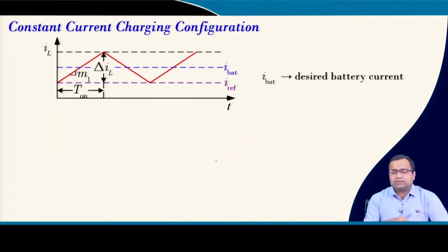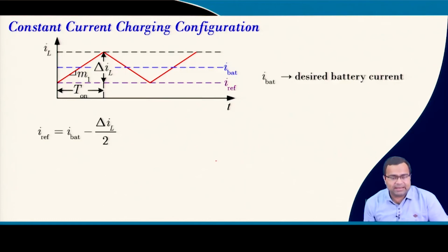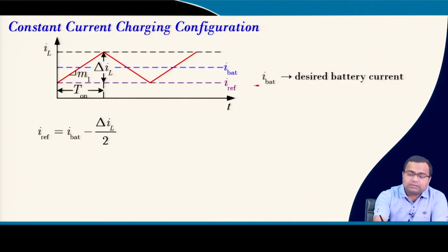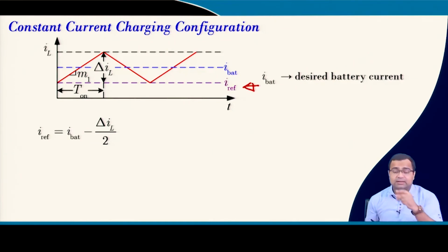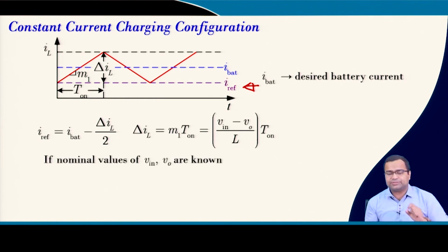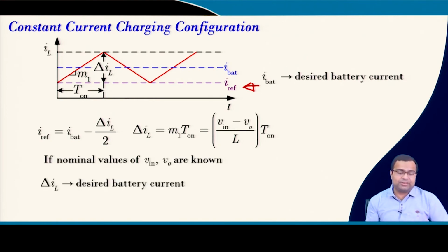Similarly, a constant current loop can be used for a battery charging application, where you take a boost converter or a buck converter, with the reference current and constant on time, and we control the valley current. We will compare this result. The ripple current for a buck converter, we know, is (V in minus V0) by L, times the on time.